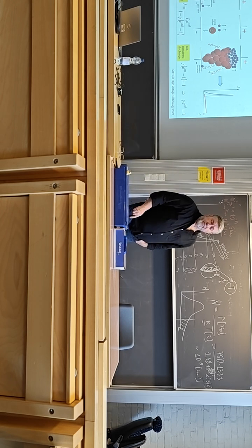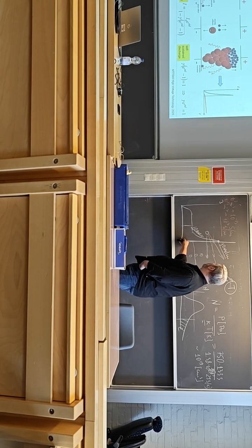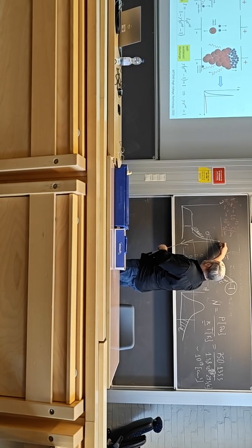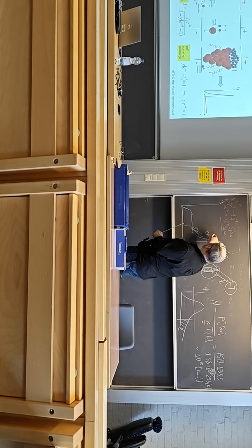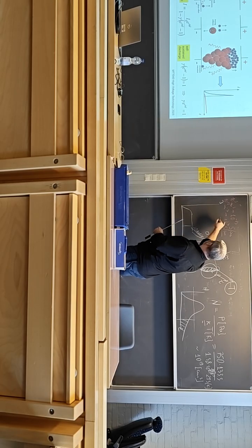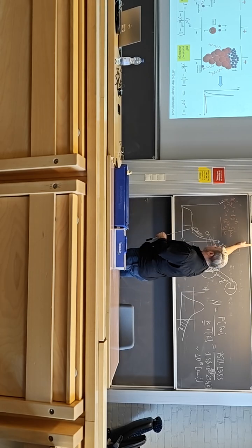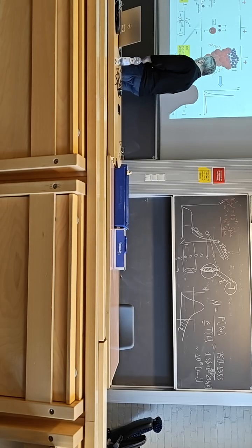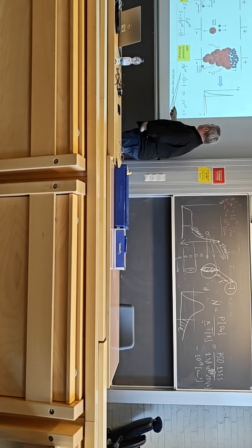Self-sustaining discharge, when this happens, actually we can say virtually the current goes to infinity. So it's a very sharp transition here. Depending on the impedance of the external circuit, you may have some kind of significant drop here. But mathematically we can assume that the current goes to infinity. There's the breakdown. At what condition does it happen? When the denominator is 0, right?